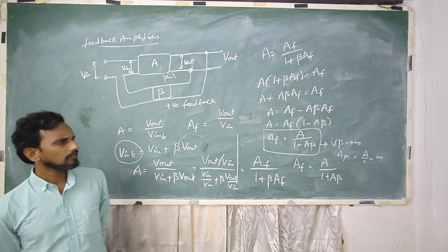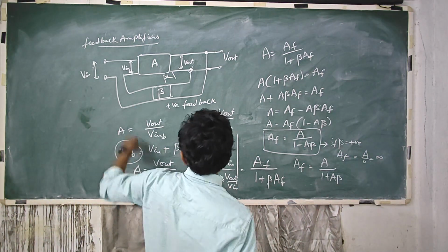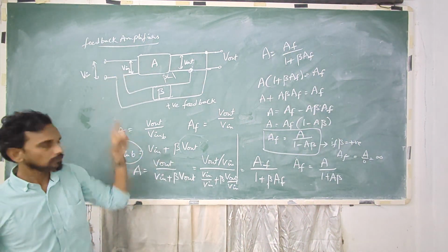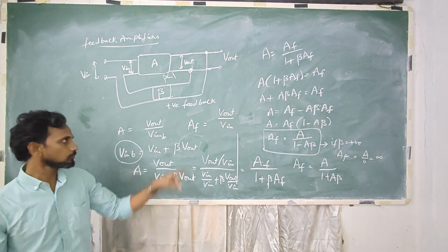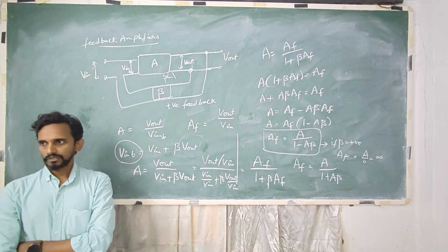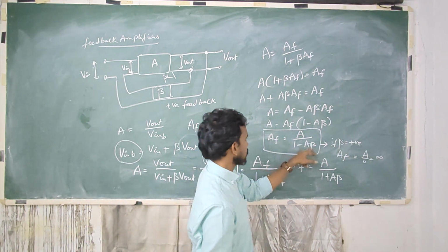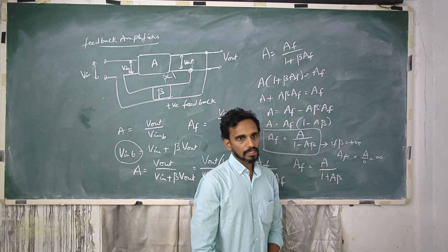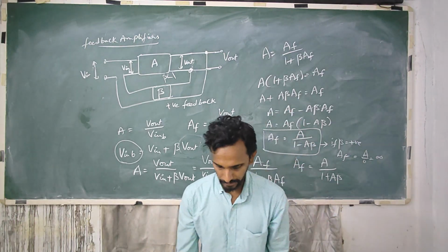Okay, current may vary. And adding it in series here in the input. So here in the input section voltages will add up, and output section voltages will remain same. Okay. So under those conditions, if I maintain A beta product is equal to 1, then I'll get an output signal without an input signal, and that condition is called oscillator.